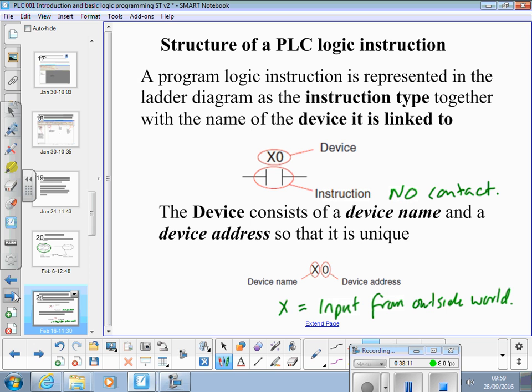On your PLCs, I think that's X0 to X7. Yeah, you've got 8 inputs. If you had more, it then goes to 10, because it's a legacy thing, the inputs work on octal, an octal base number system for some reason. Okay, so that is the inputs.